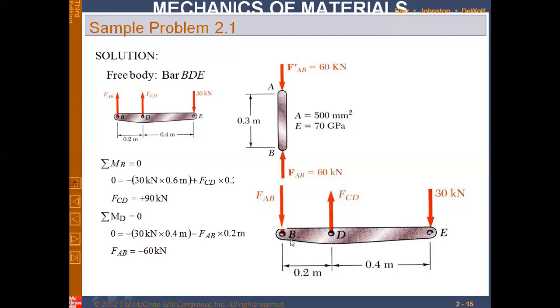So on the joint, the direction is in the downward direction. So on the link AB, at this point, the direction would be in the opposite direction. Now we have to make sure the whole system is in equilibrium. Each and every link must be in equilibrium. So if one load is acting at point B in the upward direction, in order to make it in equilibrium, there would be another load acting at point A in the downward direction.